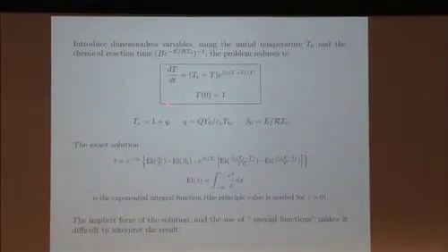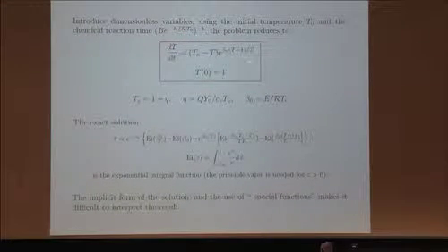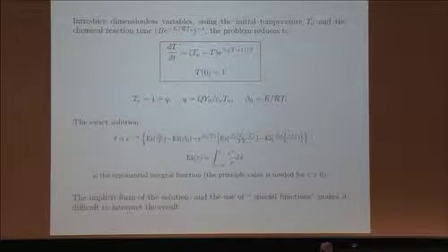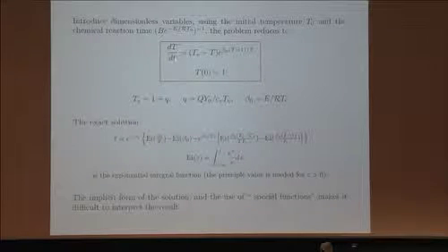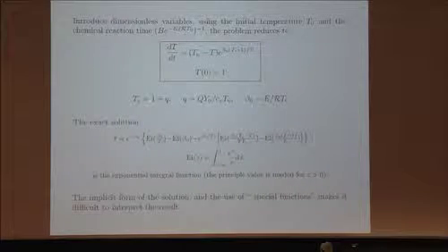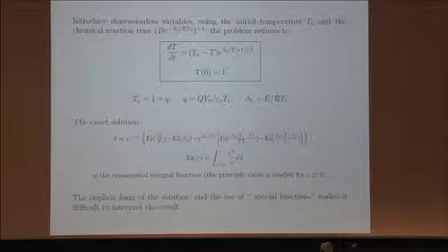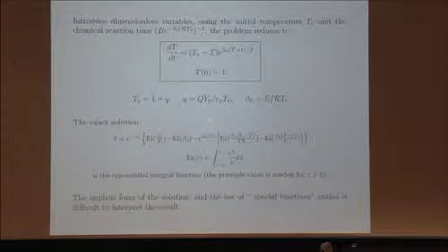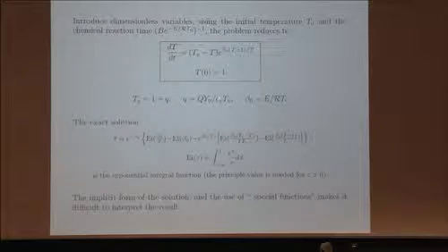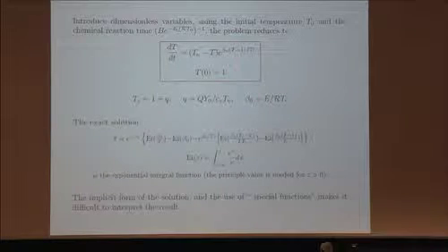In addition, we have normalized things. We have put this equation in dimensionless form. So T was scaled with the initial temperature T naught. So it starts from 1 and it goes to the equilibrium temperature. And the equilibrium temperature now in dimensionless form is simply 1 plus Q. The little q is essentially the heat release scaled with respect to the initial internal energy of the mixture, CV T naught. And the other parameter is, of course, the activation energy parameter, which appears in the exponential.